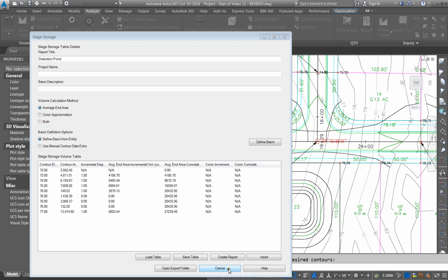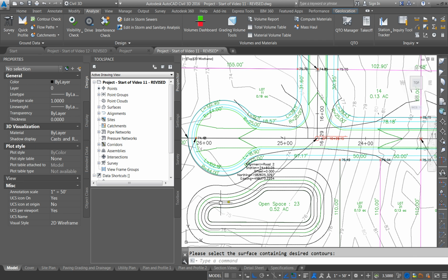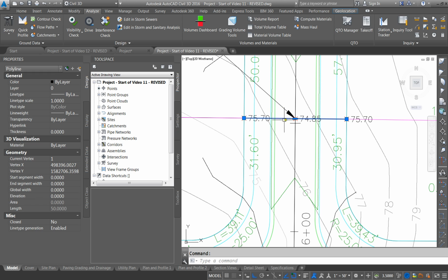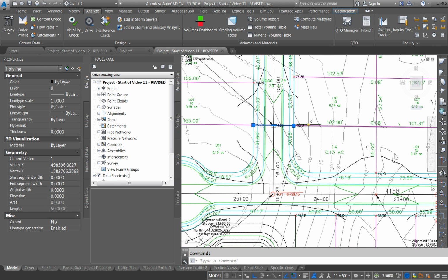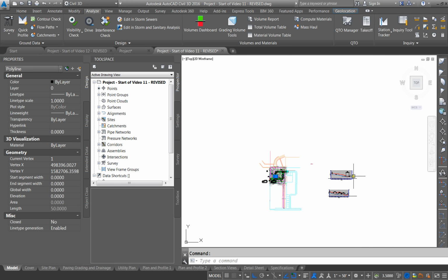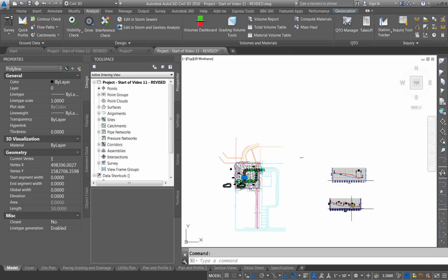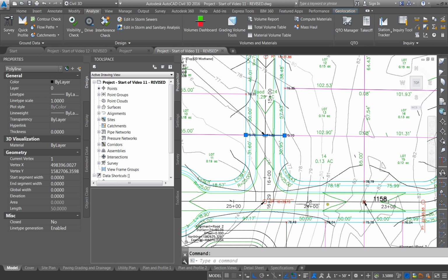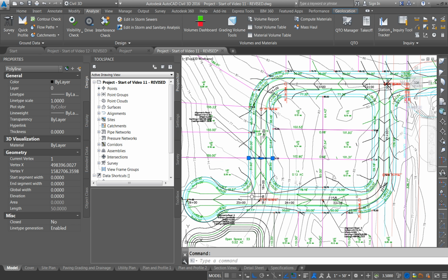and cancel. Now, the next thing I want to talk about is doing a 3D polyline to create the storm pipes. Remember, I said the inlets are going to go at the intersection or along this line where the low point is when we created our profile. In another class we created the profile, and we're going to have low points here, and where these two come together, they're going to discharge out.